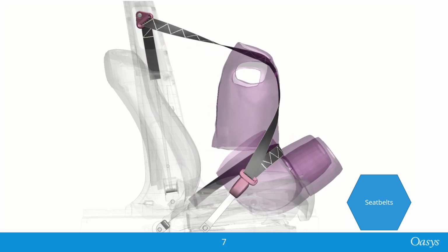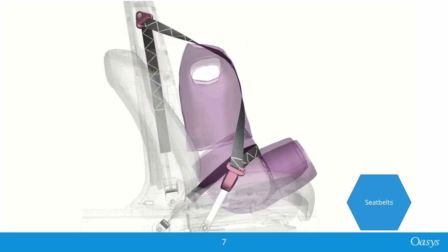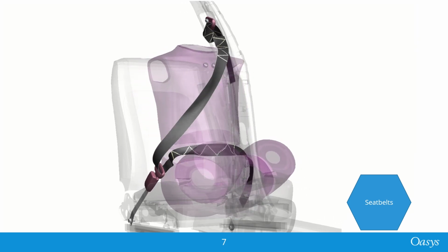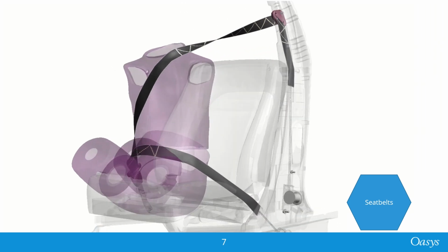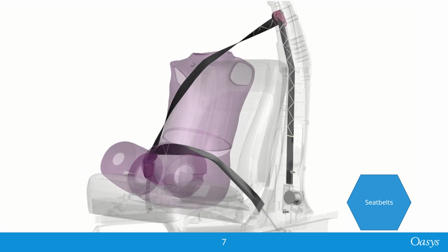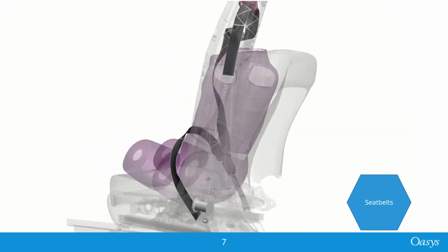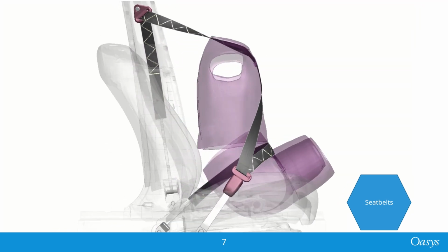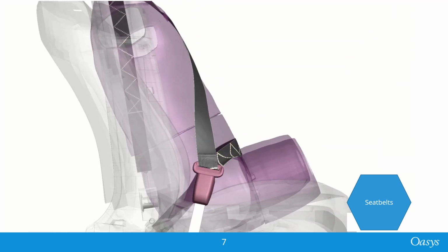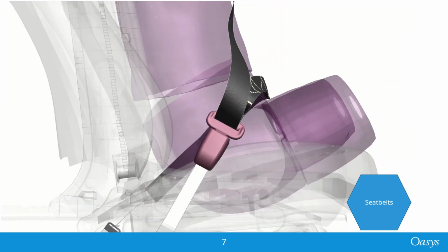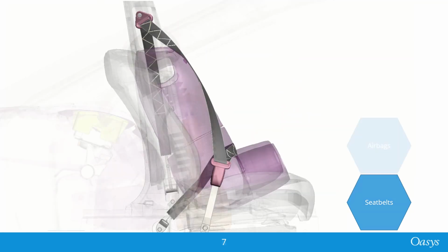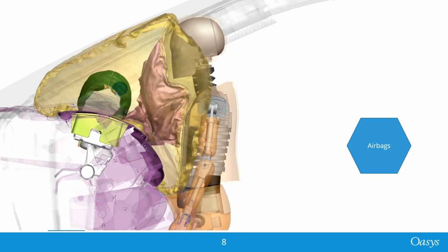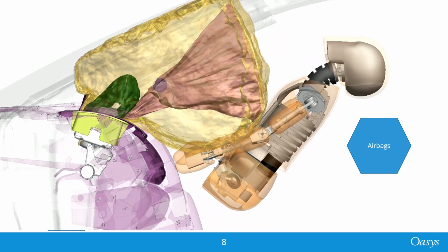We have tools for the creation and fitting of seat belts, including fully fabric belts through explicitly meshed slip rings. It's also worth noting that these tools include creating seat mechanisms, which allows you to easily move your seat into different positions. Our Seatsquash tool allows you to easily deform seat foams to remove initial penetrations between the occupant and the seat. We have a powerful airbag folding tool available as an optional plugin to Primer. This is called J-Fold.